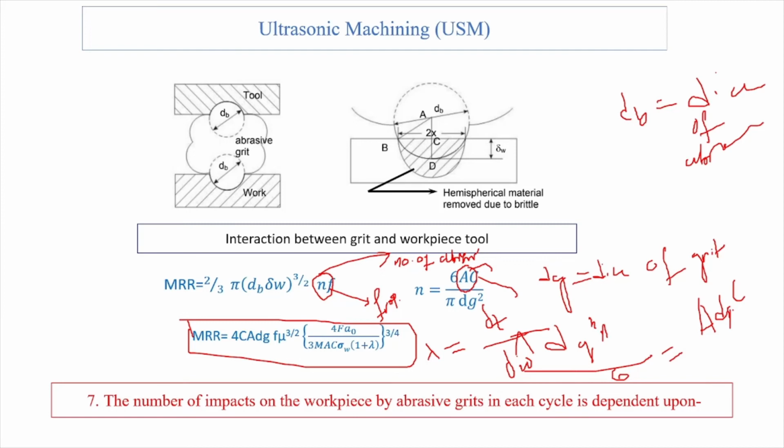And the transducer, whose working we have already seen in the USM process. And last is the horn or concentrator. What is the function of the horn? The horn or concentrator amplifies the vibration to the required amplitude. With amplification, the frequency will be 10 times greater than without amplification.